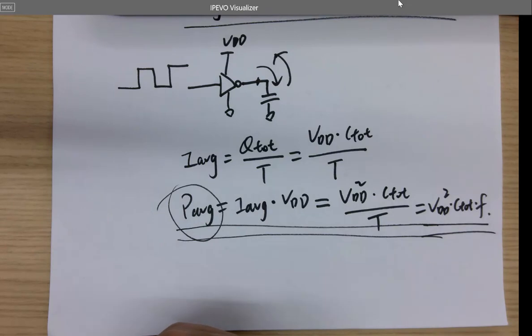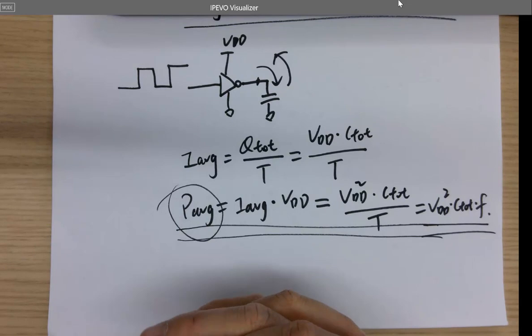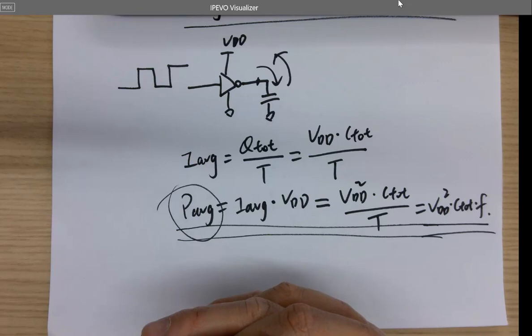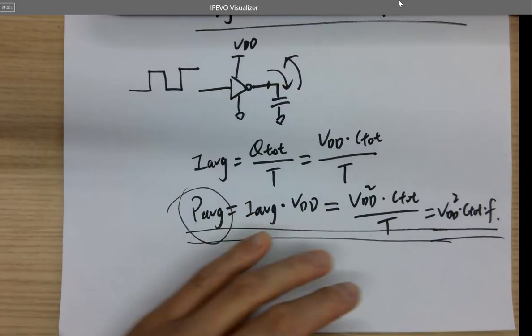So why did all the engineers spend so much effort to reduce the VDD for the circuit? Because it's lower power consumption, right? So if you can use 1 volt, don't use 3.0 volts. Even though you connect the 3.0 volts to the microcontroller, if the microcontroller is under 180 nanometer technology with TSMC, it has an on-chip regulator.